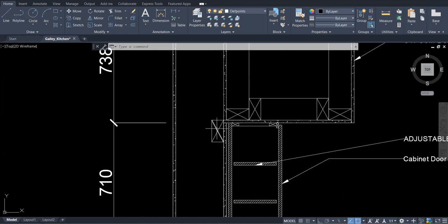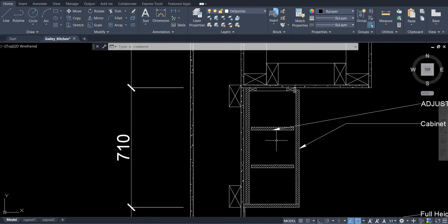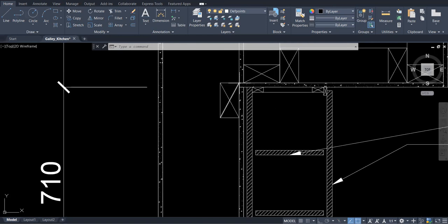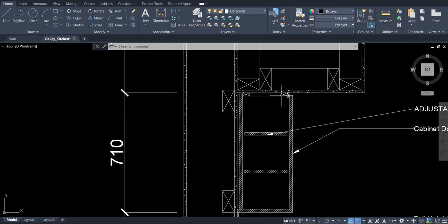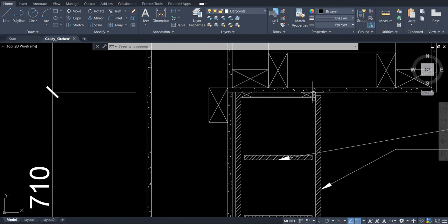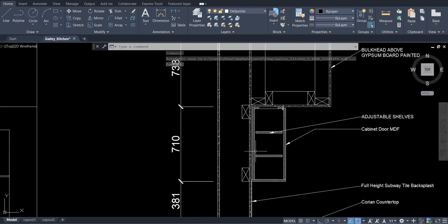Now the information is that we use those blocks to fasten the position of the cabinets, because those cabinets are going to be heavy, and they're going to be also heavy with the type of utensils that you're going to put in. So they have to be fastened with something blocky like those wood blocks, and usually we use nails to fasten those. Okay, so that's why you're going to see all of those small size blocks or big size blocks, because that's basically what we need to do.